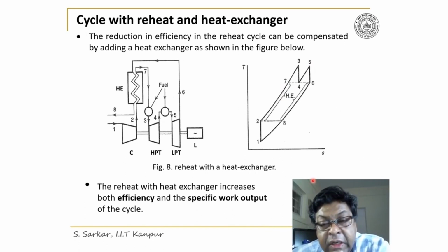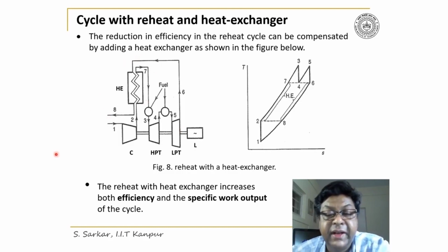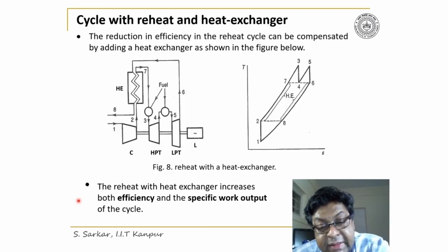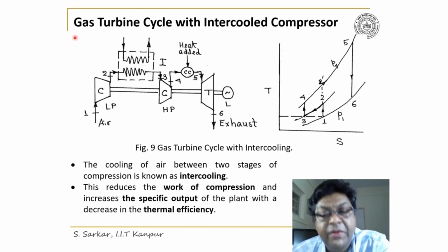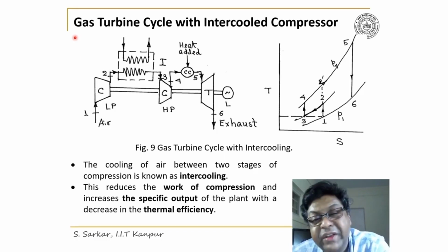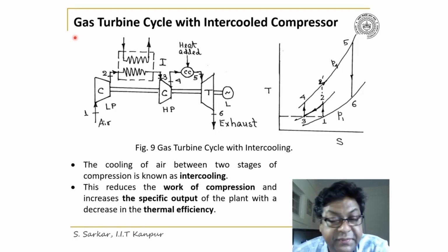Therefore, we have utilized a considerable amount of energy because of the addition of the heat exchanger, as illustrated before. Thus, we can conclude that the reheat cycle with a heat exchanger increases both efficiency and the specific work output of the cycle. Now I'll discuss the gas turbine cycle with intercooled compressor.